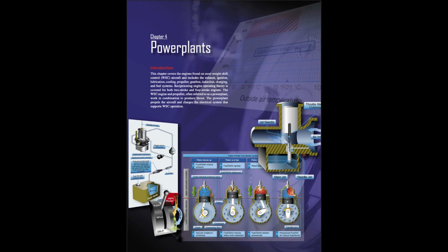The powerplant system is composed of the engine, gearbox, and propeller. It is a key component of a WSC aircraft and should be maintained according to both the engine and airframe manufacturer recommendations. Pre-flight information, along with maintenance schedules and procedures, can be found in the Pilot's Operating Handbook (POH) for special light sport aircraft (SLSA) and/or maintenance references from the manufacturers. Engine inspections and maintenance must be performed and documented in a logbook. A pilot should review this logbook before flying an unfamiliar aircraft.